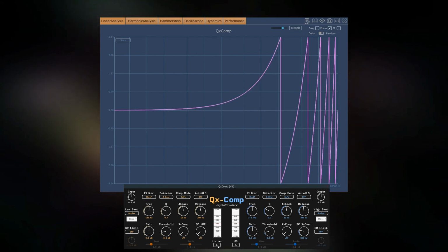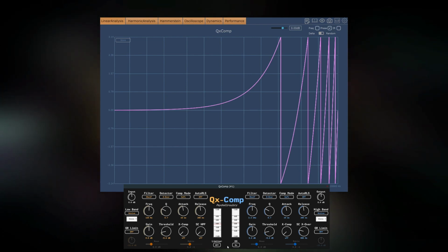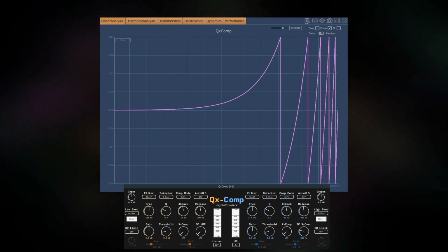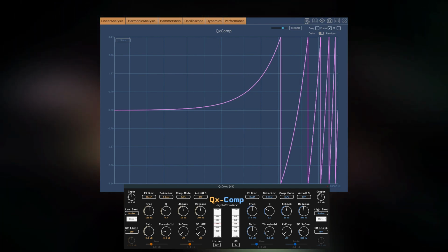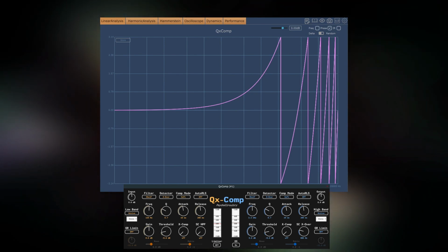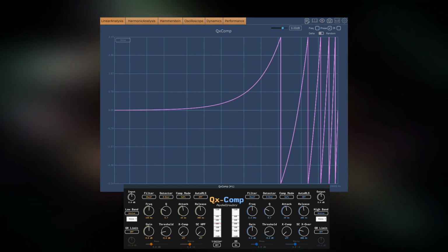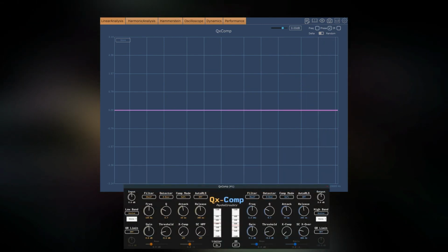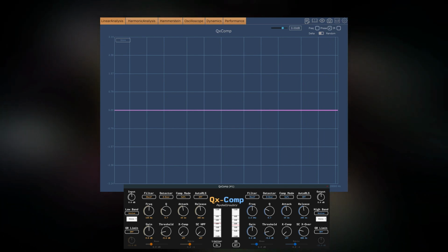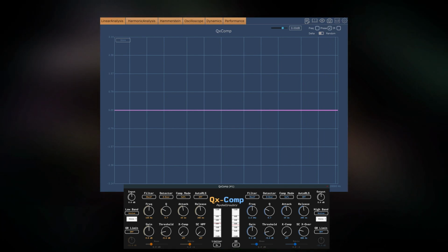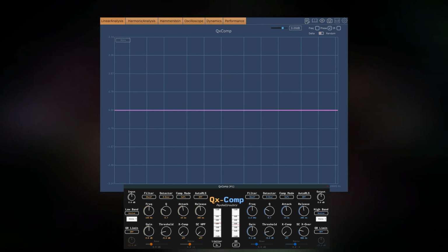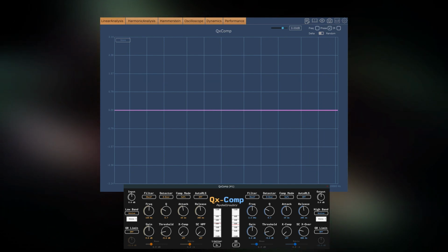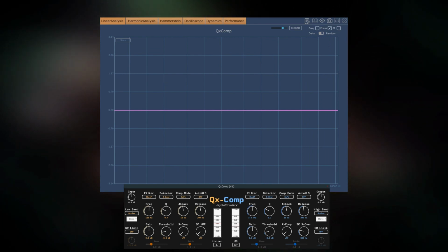The phase response in Plugin Doctor is also exacerbated by the subsample latency of the polyphase oversampling, which cannot be accounted for by the integer-based sample offsets that plugin hosts use for latency compensation. Really, the phase disturbance and subsample latency will only have a negative impact if we attempt to blend a dry signal in parallel. But since this primarily operates as dynamic EQ bands, parallel operation seems mostly redundant, as we could just lower the gain of the bands for less effect, instead of using a dry signal blend. So this method seems appropriate for this design.